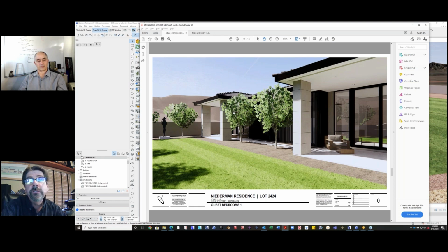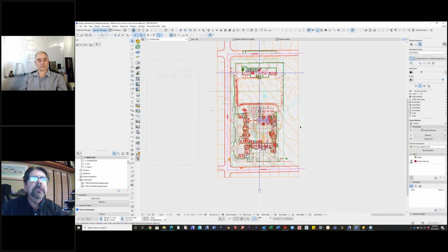And then you can do that 20 times in one SketchUp file by moving your little patch to a neighboring location, and you can build, and I've done that, that was the third way. You can build a mesh. Once you come out of SketchUp, it'll act as all one mesh when you load it into ArchiCAD, because at that point it's an object.